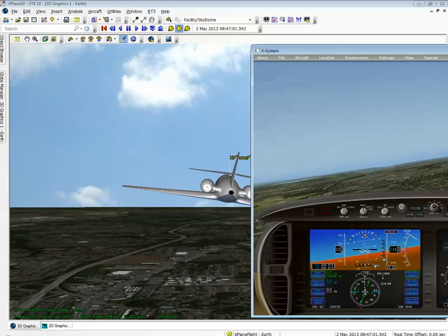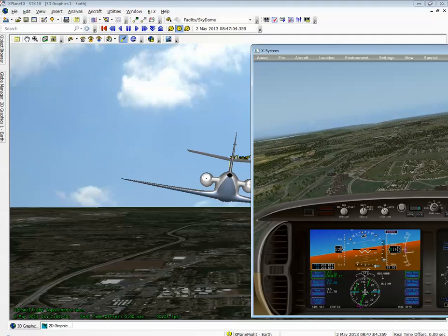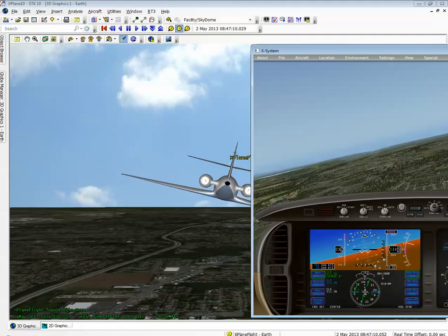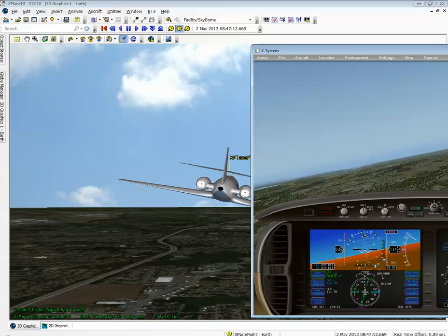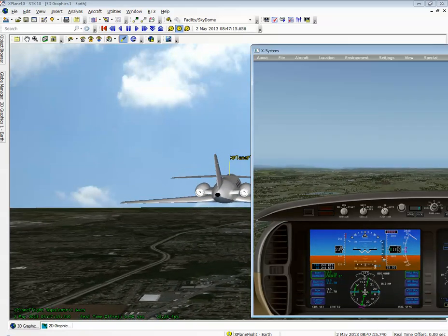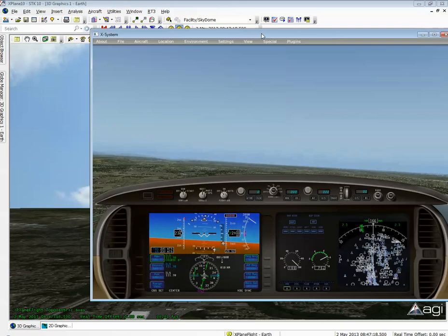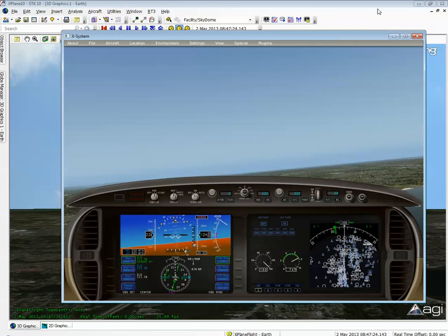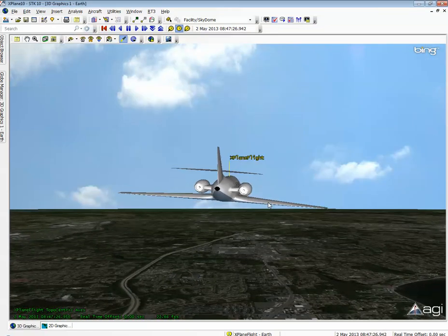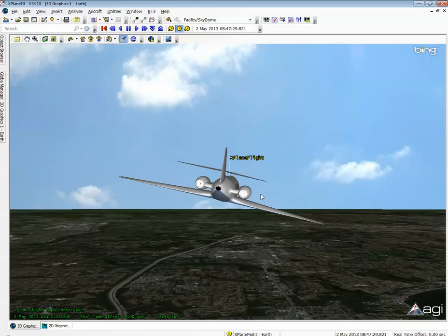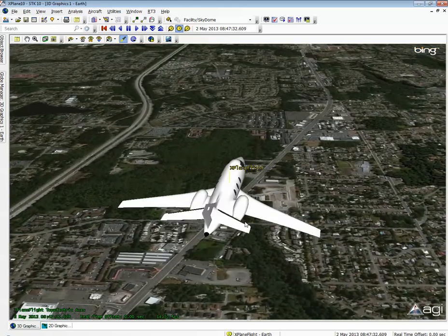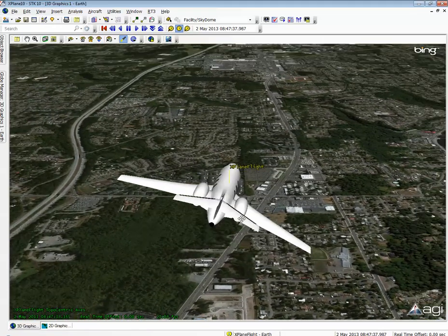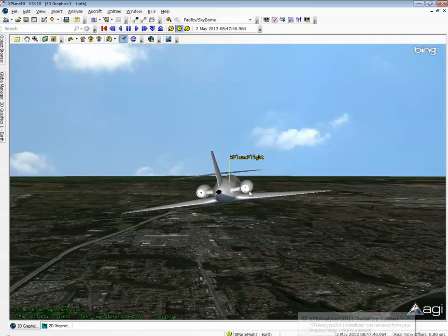So this gives me a really unique capability that STK provides, because now I can utilize things like sensors, transmitters, receivers, and I can do a lot of my typical STK calculations. This is something that I can do post-mission, or in some cases I can even do this in somewhat of a real-time sense. So in this case, I've got my aircraft that's flying around. I seem to have some reasonable response from the aircraft as I'm flying, so I can see my position and orientation and things changing as I'm interfacing with the joystick here.